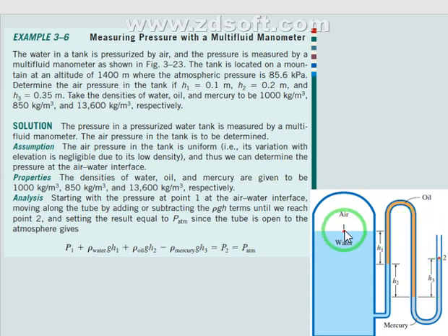So this is the water surface and this is the oil surface. The water surface is higher than the oil surface, so I must use positive rho water, I use the rho of the original, the left liquid, g, and h1 is the difference between them.